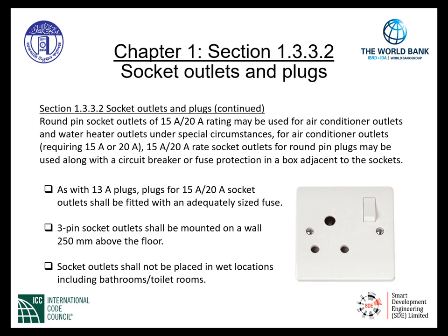3-pin socket outlets shall be mounted on a wall 250 millimeters above the floor. Socket outlets shall not be placed in wet locations, including bathrooms and toilet rooms alike.